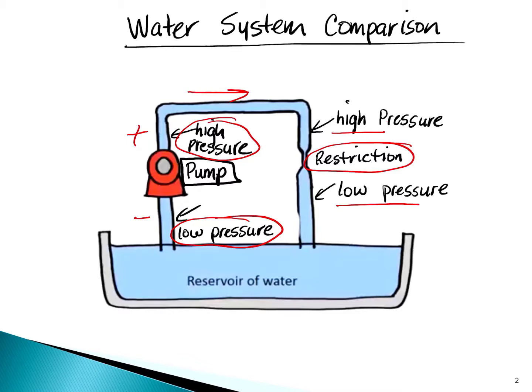So one thing to note right away here is, notice how with the pump there's a pressure difference or a pressure differential, and it will always be there even if you were to stop flow entirely with a valve in here or a shut-off valve to turn it off. That pressure would remain.